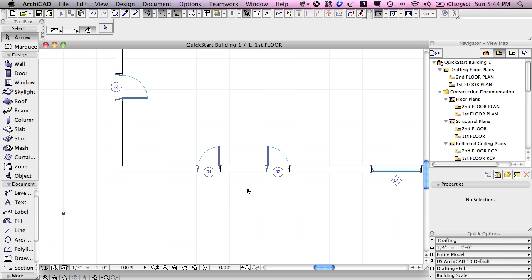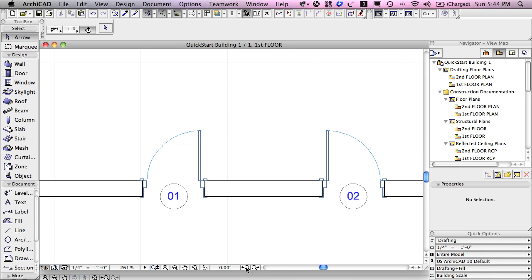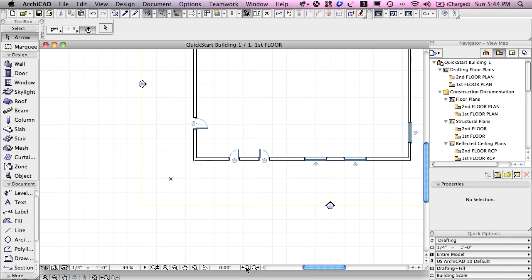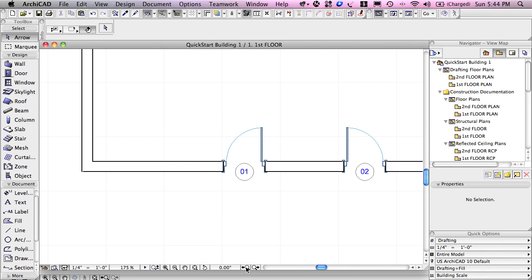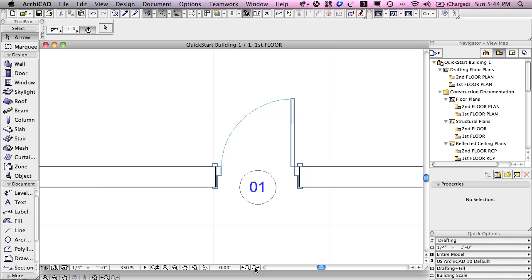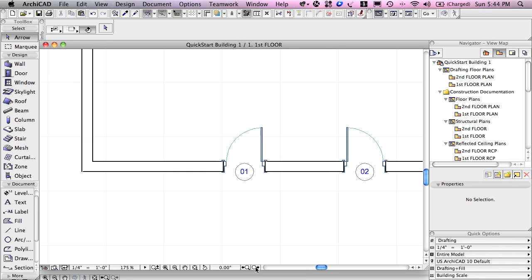Now, I've been zooming in and out using the plus and the minus, and occasionally using the hand or pan tool to move sideways, and of course using the fit in window. There are a number of other options here. We don't need to go into most of them because these 4 are going to get us pretty much as many locations as we need. But this one is very interesting. Previous zoom, I'll click on that, and I'll click on it several times. And it's like a history of where I was looking as I click on it. And then there's next zoom.